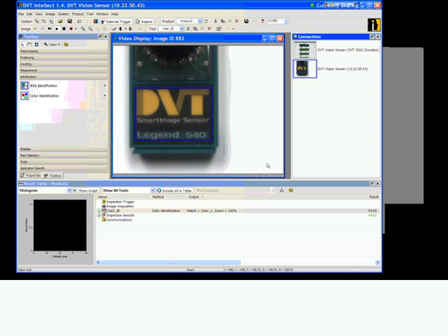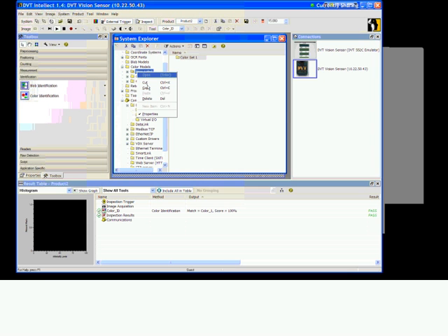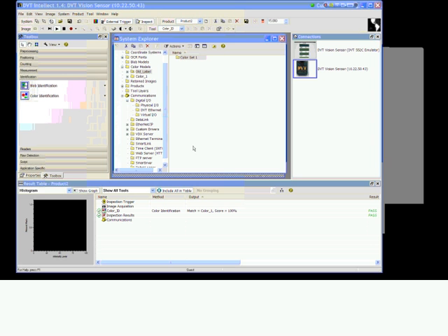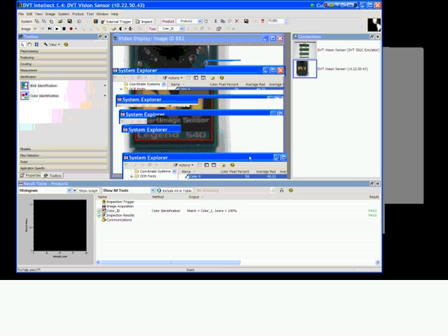And if we look at System Explorer here, under color models, and going to delete this previous test. And here's our color 1. If you look at color 1, it actually has various colors that were learned, right? With their individual average red, green, and blue values, and a certain color percentage. So color 0 is present as 50% of the part.